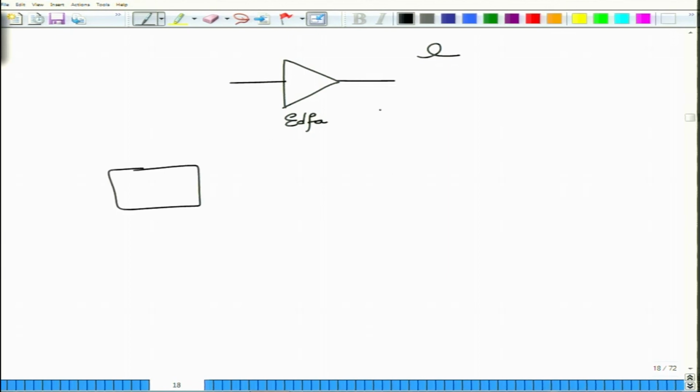So, this is also a WDM component by the way, and as we have also seen, the EDFA requires a pump to operate, and this pump is usually a laser diode sitting at 980 nanometer. So, you need to have a signal coming in at 980 nanometer on this blue line, and the signal which is at 1550 nanometer should also come in on the red line, and you need a device which can combine both the 980 nanometer signal and the 1550 nanometer signal, and then pass it on to a single output.